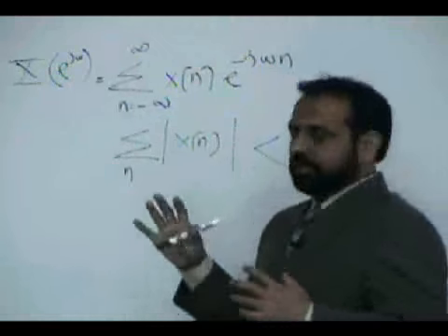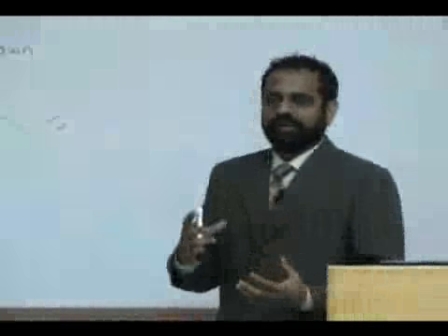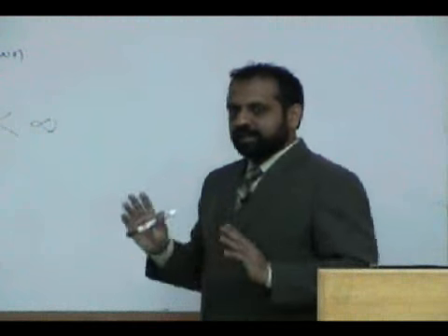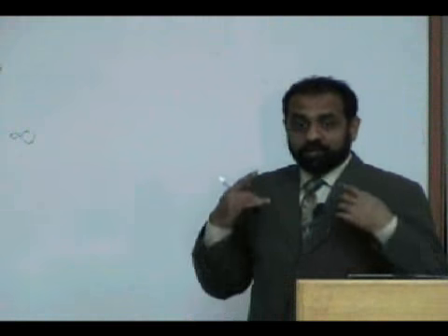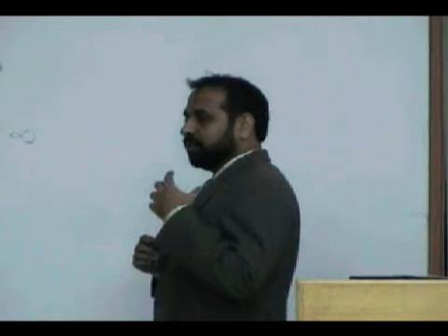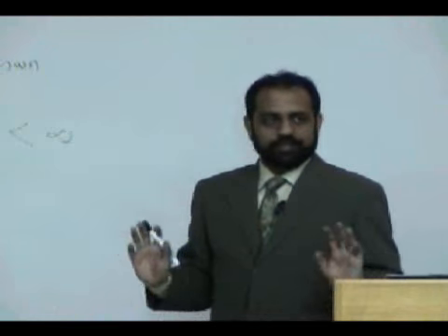So people have tried another transform by introducing another factor in the signal which brings the absolute summation to some finite number. For finite signals you don't care, because finite signals are always absolutely summable. Our only worries are about the infinite signals, and in infinite signals you deal with nothing but exponentials, in signal processing.